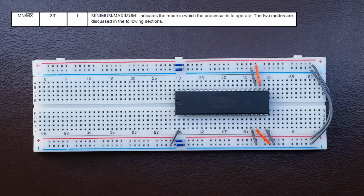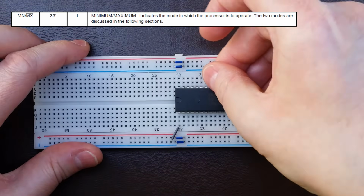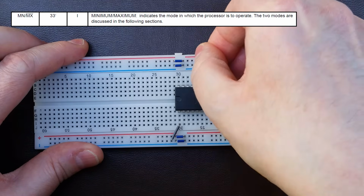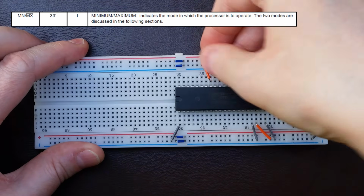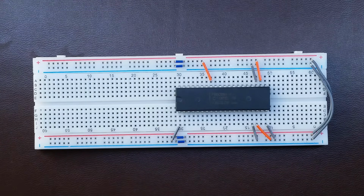The maximum mode is appropriate for more complex designs where the control signals are generated by an external controller chip. It is required for systems using, for example, the floating point coprocessor x87. Our design will be using the minimum mode, which means that pin 33 needs to be held high. After setting the bus mode, we can carry on with the rest of the pins.